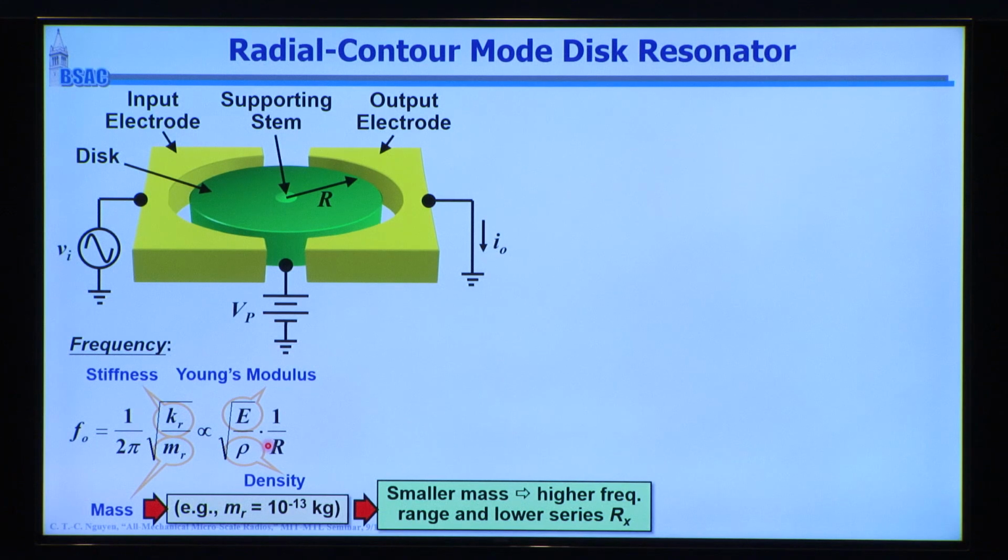And so that's a nice thing about this device, because what it tells you, unlike an F-bar where the frequency is dependent on thickness, the frequency of this device is dependent on a lateral dimension, which is CAD definable, which means you can make all sorts of different frequencies on a single chip. That's something you cannot do with the F-bar technology that I just talked about. That's making gobs of money. So if you can make this work, think of what you can do.